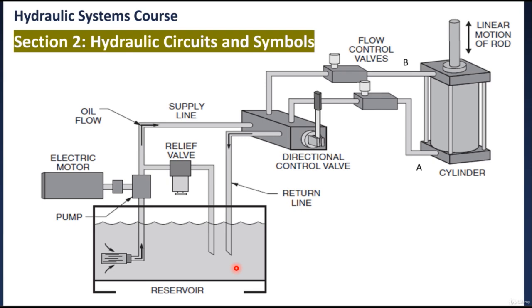Typical hydraulic oil used is generally a high density incompressible oil. It is then filtered to remove dust or any other unwanted particles, and then pumped through a hydraulic pump. The capacity of this pump depends on the hydraulic system design, and these pumps generally deliver a constant volume of fluid.